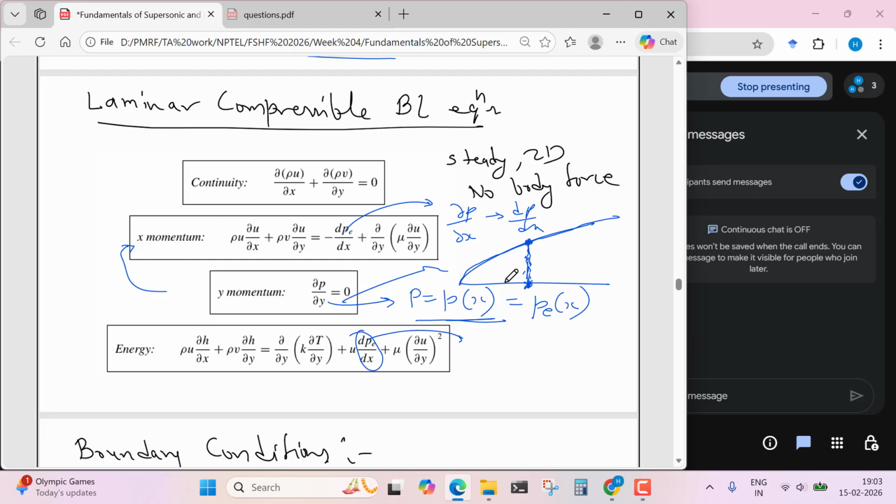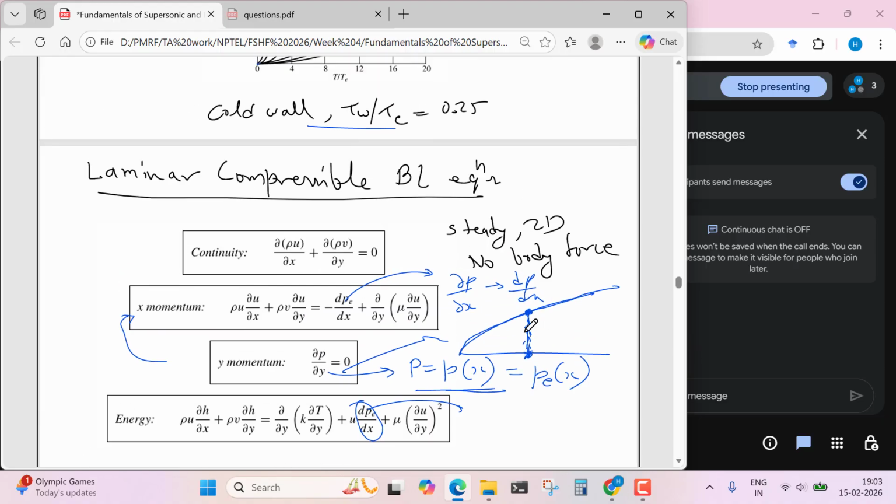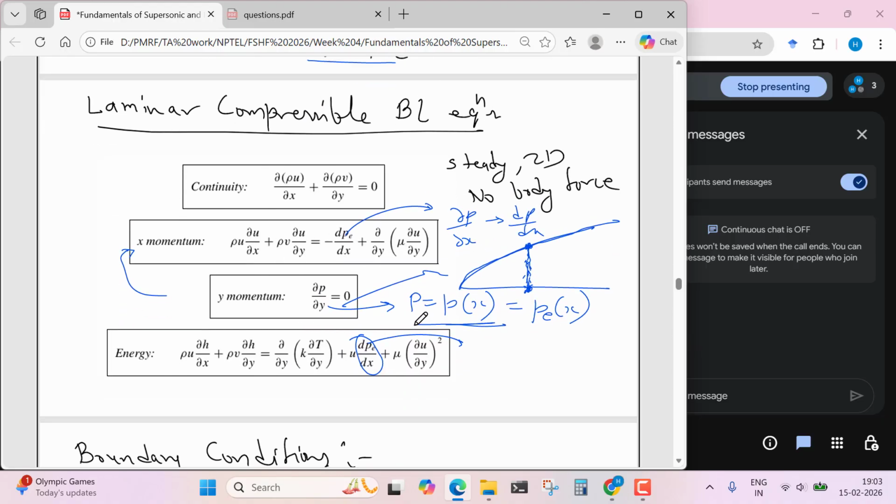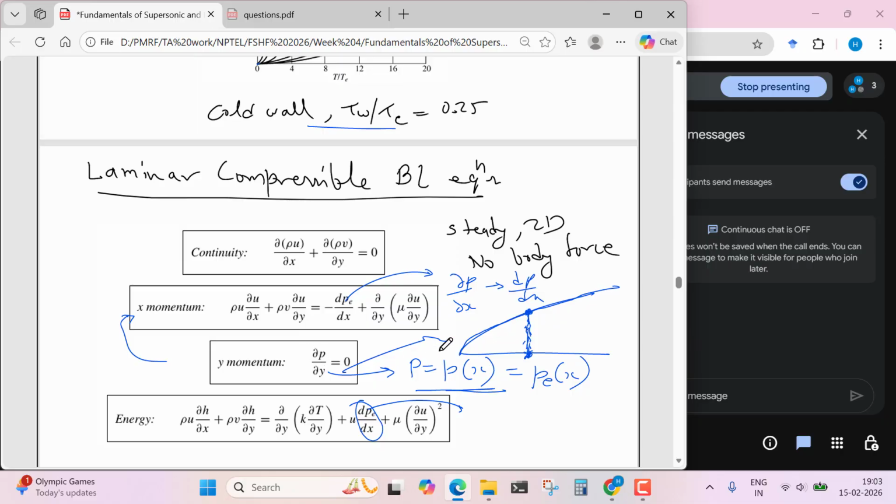Why in hypersonic regions is ∂P/∂y non-zero? Is it due to the temperature gradient along y? It will be mainly due to the high temperature effect, so it will not be equal to zero. Even in supersonic flows, the y temperature gradient is not very strong. So that's why ∂P/∂y is zero.